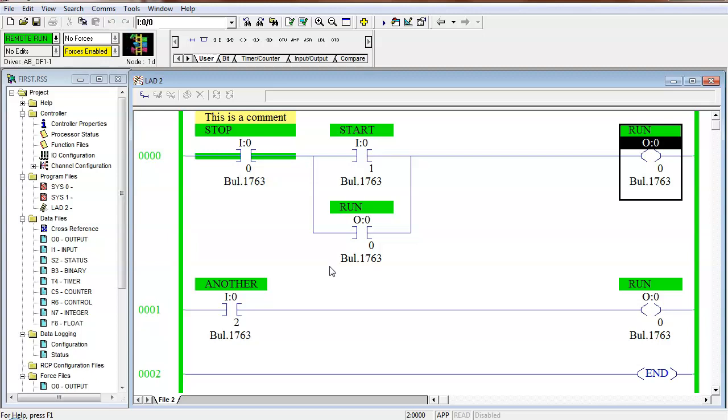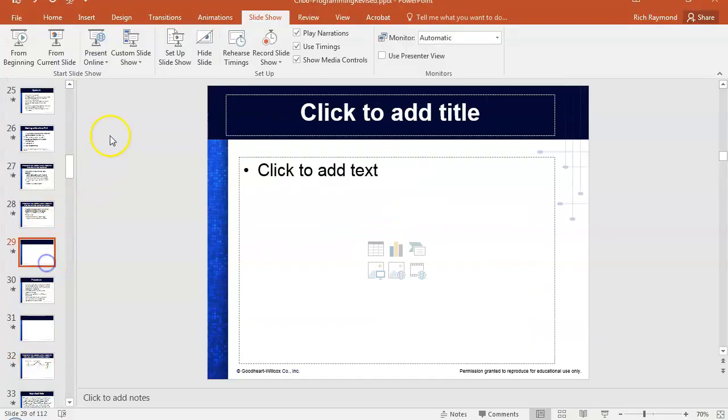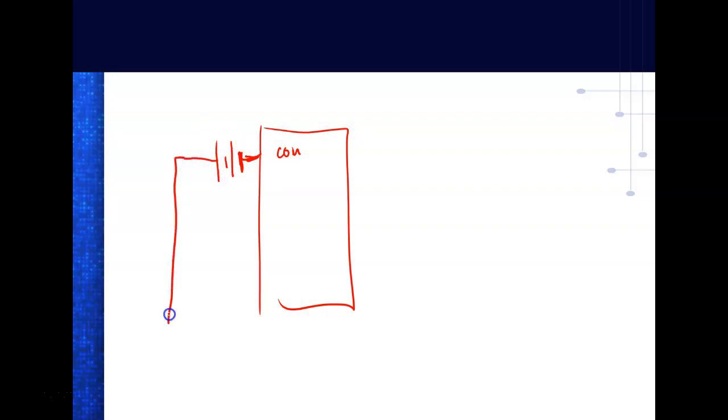So what I've done is I've come over here and done this. My PLC inputs are sinking. On my inputs, I've carried my plus over. So my common, I've got my minus pointing towards my common on your input. And then I've run the plus down.